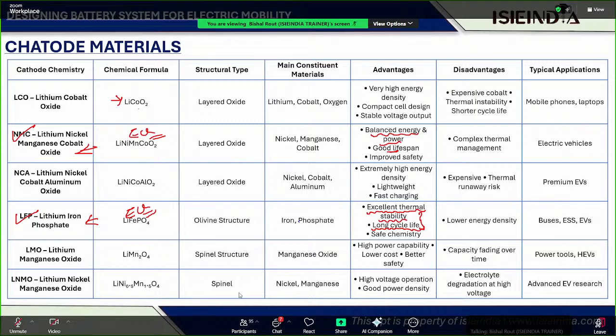They show more internal resistance when charging and discharging, right? And below a certain point, they were very reluctant to charge, and very reluctant to discharge as well, right? We have to forcefully push a huge amount of current, and only then will it discharge. And in a practical vehicle, we cannot forcefully push a huge amount of current, else our vehicle or battery will get heated, or the battery might get damaged, right?